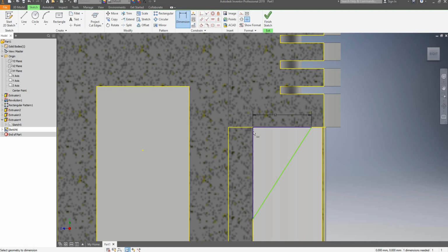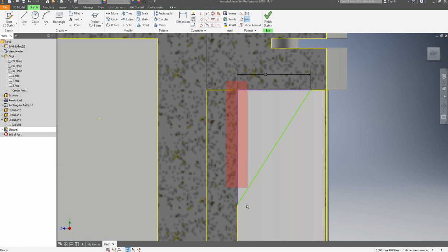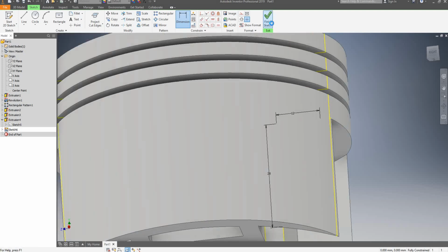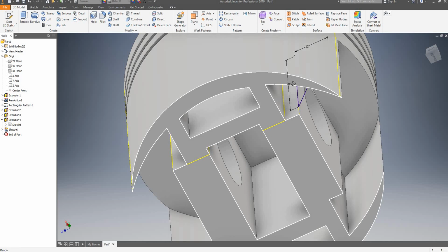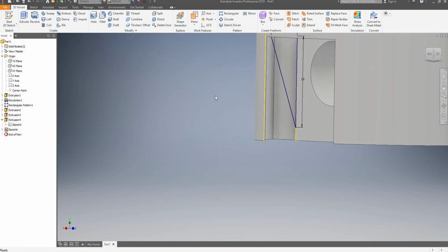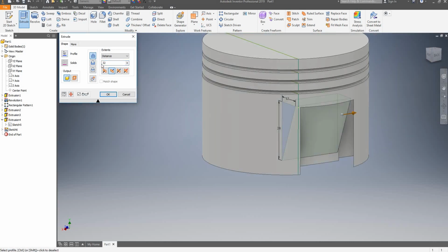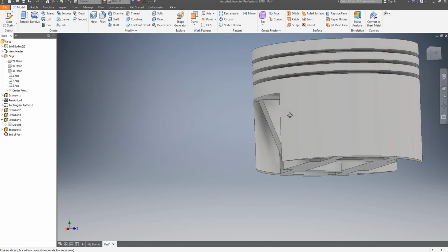And it's not letting me select this one. I'll try the same thing again. And this one is going to be 28. So that seems correct. I'll finish my sketch. I will now use my extrude tool again. So type in E, select your feature, and I'm going to extrude it in the opposite direction, 5 mil. So I'm going to click on OK. So I've got that already.